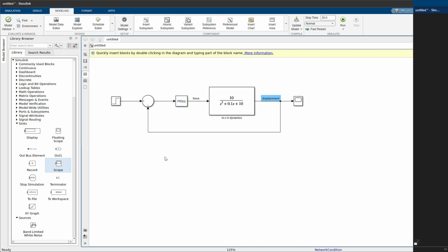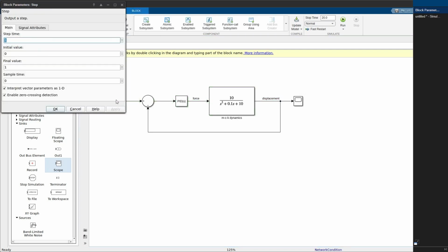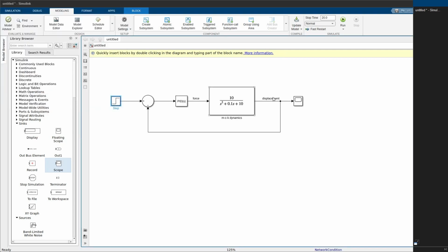Then we are applying a step function of unit height, and it will jump from 0 to 1 at time equals 1, and we would like the displacement to track the step function. Obviously, because this function is discontinuous, and because we have inertia, it will not be possible to perfectly track it, but the system will seek to reach the steady state step function if you design the PID controller gains properly. Overall, the tracking error is computed, and the PID controller will then decide how much force to apply to the system, and the system will react to that, and this loop will keep updating or refreshing,